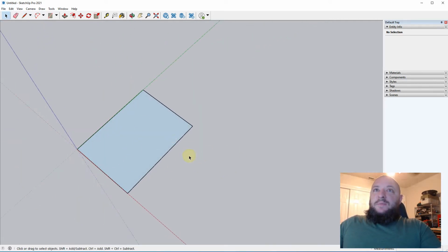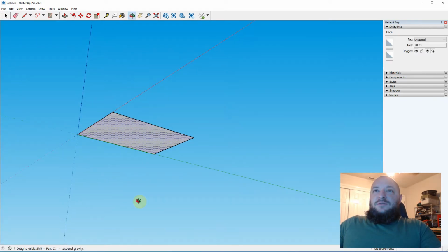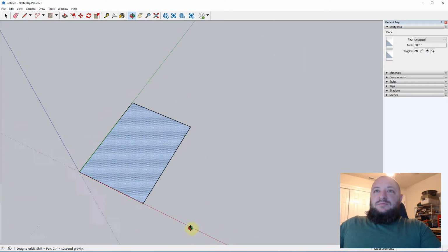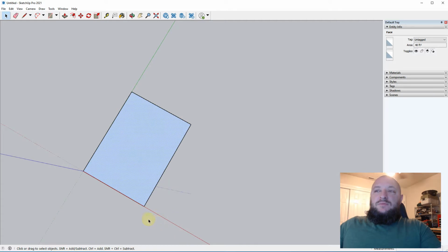Now, my OCD for reasons is going to actually flip this, and you can see right here when I talked about the default material that comes on faces when you create them. There's a light side and a dark side, which is shown up here. And so right now you can see that there's a light side right there, and if I actually just do half of this and reverse the faces here, you can see there's a light side and a dark side, which corresponds to those.